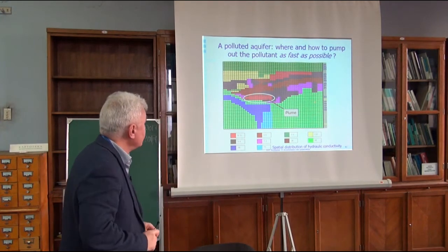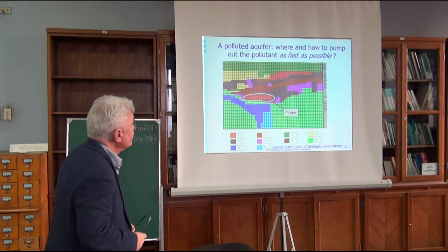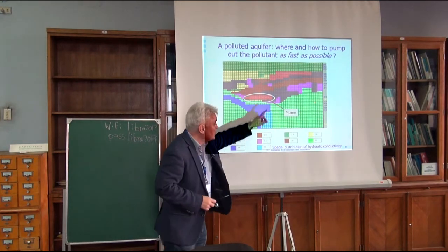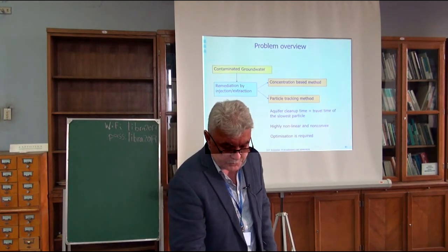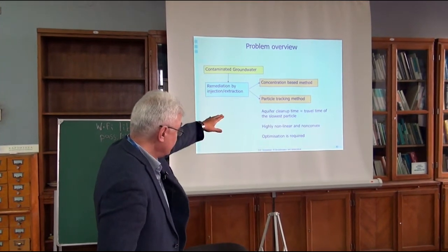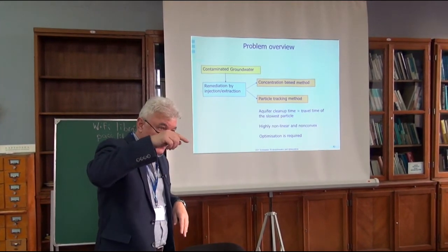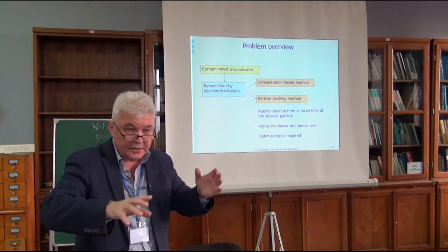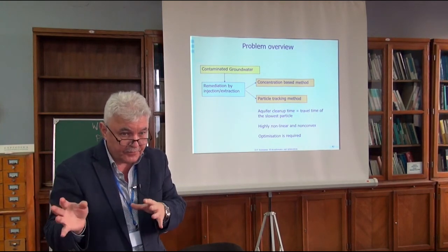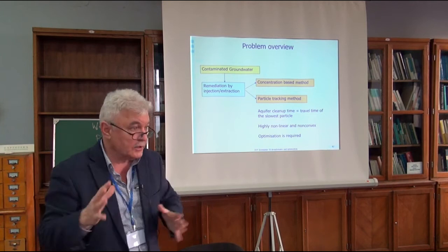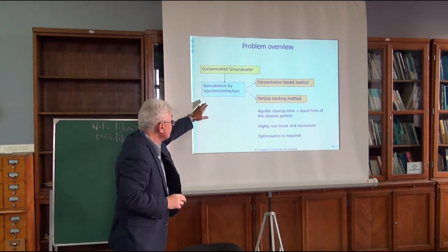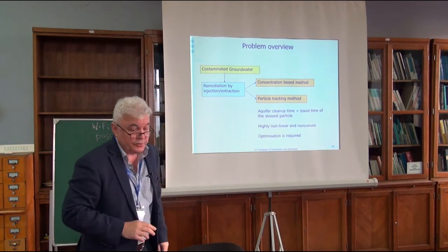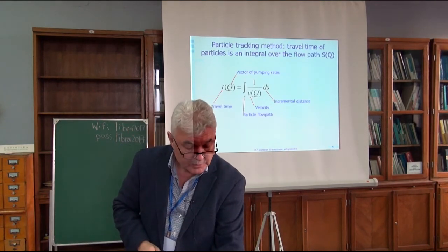So I have to move quick here. That was a plume which we had to remove. We used ModFlow, which has particle tracking methods implemented. We throw virtual particles into the water, they move, and when 95% of particles are moved out, we're happy, it means all clean, okay? That's by injection and extraction of water. This is how you move.